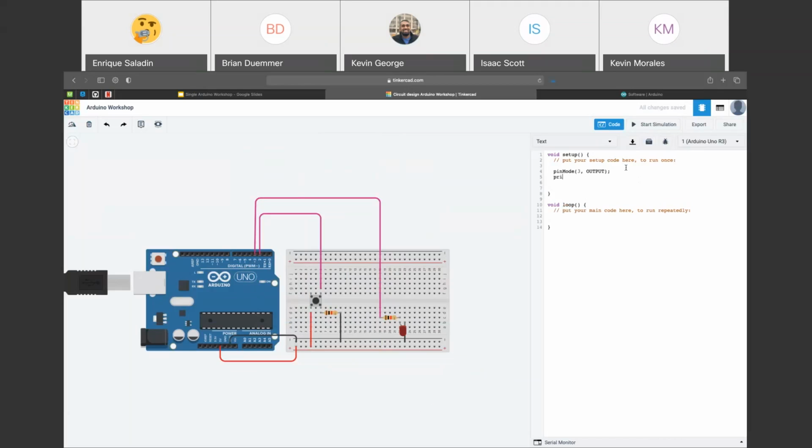We're going to start again with our second piece of hardware, the button. That button is on pin 2. So instead of output, since this is an input device, we're going to use the input label. Our button is our input, which our microcontroller is going to receive data from. So our two pieces of hardware are defined: our output as the LED, and our input as the button. So we move on to our looping function.